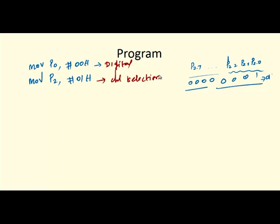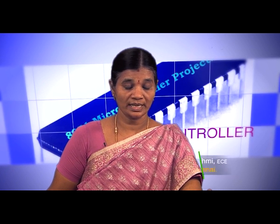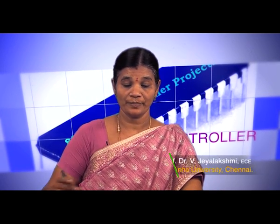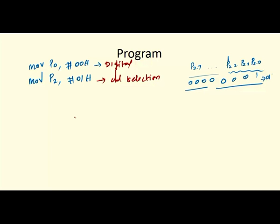Okay. So, I have initialized one of the channels, then I initialized the channel selection, right. Then what do I have to do? Now, I have to start the process. To start the process, I first have to activate the ALE signal. ALE is connected with P 1.0, then SOC is connected with P 1.1, EOC is connected with P 1.2.